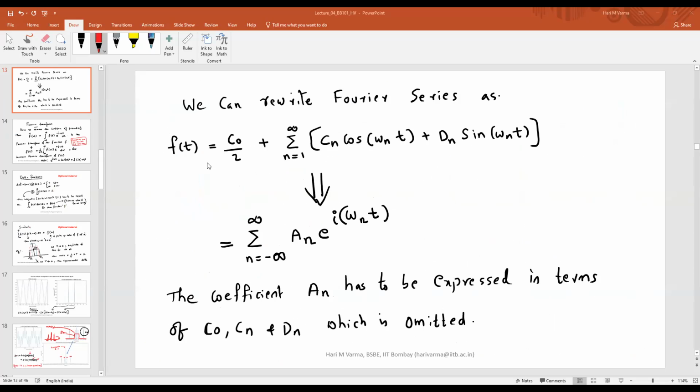So if you have a time domain signal f of t, then I can represent it using a weighted sum of the cosines and its harmonics, or sines and its harmonics, or in general, a weighted sum of the complex exponentials, right? We have seen all this stuff. And when you add all of them, basically you can switch back between these two. Either you can use f of t, or I can equivalently represent f using the coefficients a n or d n, right? Which is called the Fourier representation, or in terms of complex exponentials.